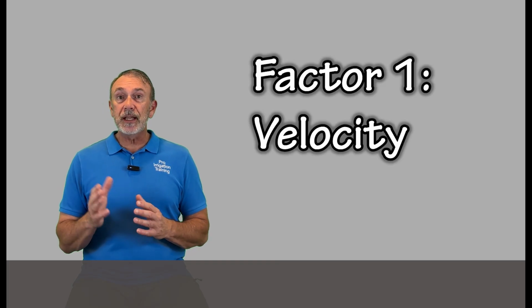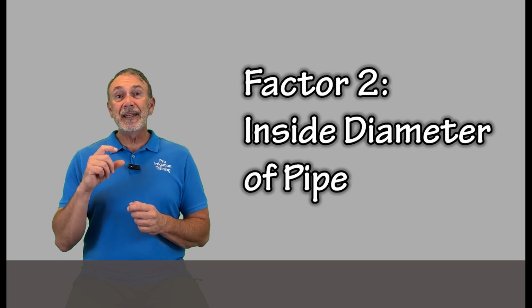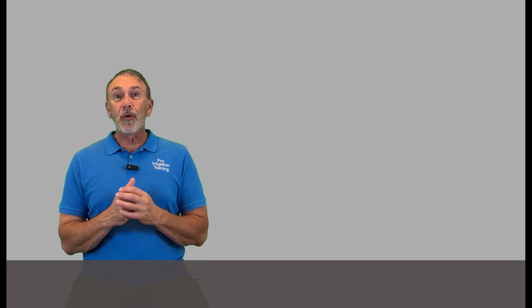Now, there's four factors of friction loss. The first is velocity, which we spoke about in the previous lesson. The second is the inside diameter of pipe. So if we're desiring the same amount of flow and we're going to use a 1-inch pipe, it's going to have a certain amount of friction loss. But if we move up to a 1.25 or a 1.5 pipe for the same amount of flow, it's going to have less friction loss because proportionately inside the pipe, you're going to have less of the surface of the water touching the inside of that pipe.